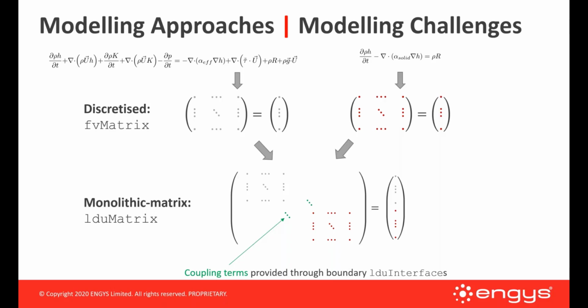And the reason why we want to do that is because we want the fluxes between one region to affect the physics in the other region. And so this coupling term within the matrix allows it to be implicitly coupled. That way, when we solve the AX equals B system for this entire system, it's much faster and more stable. So that's the meaning behind the implicit coupling.